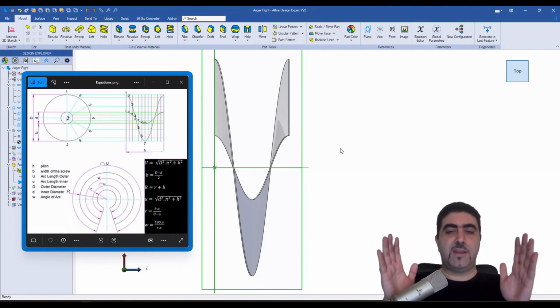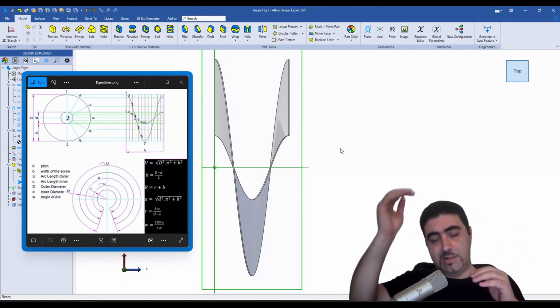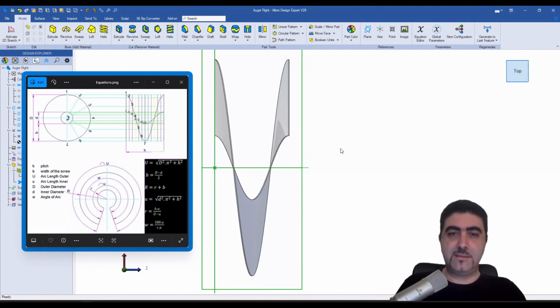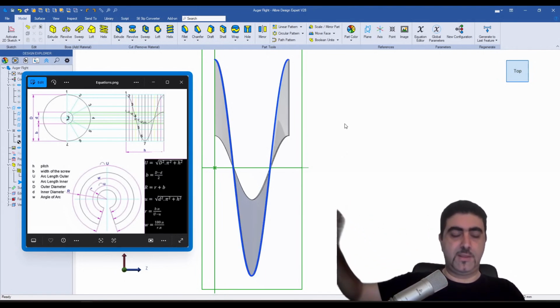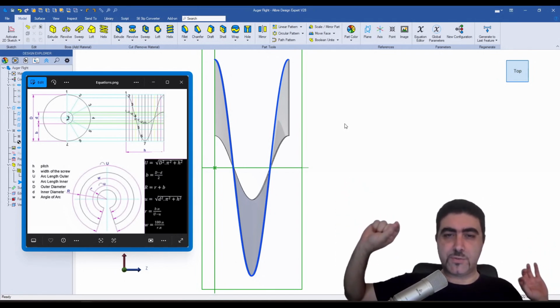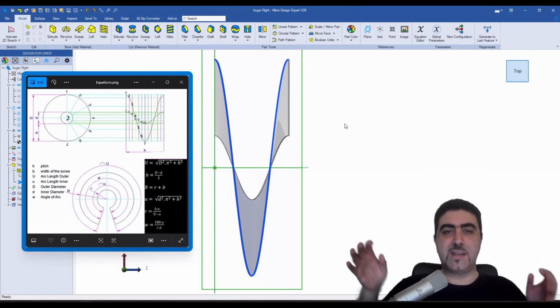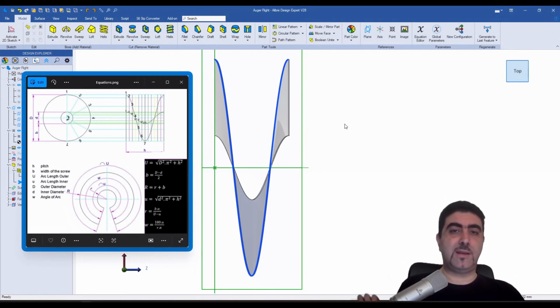The vertical sides of that rectangle would be the pitch, because that's how high up you're climbing along that cylinder. And this edge would then trace a straight line from the bottom left to the top right along this unrolled cylinder. And that straight line would create a right angled triangle.